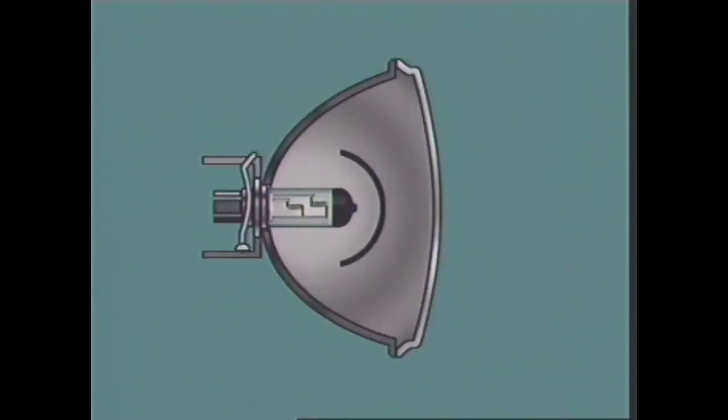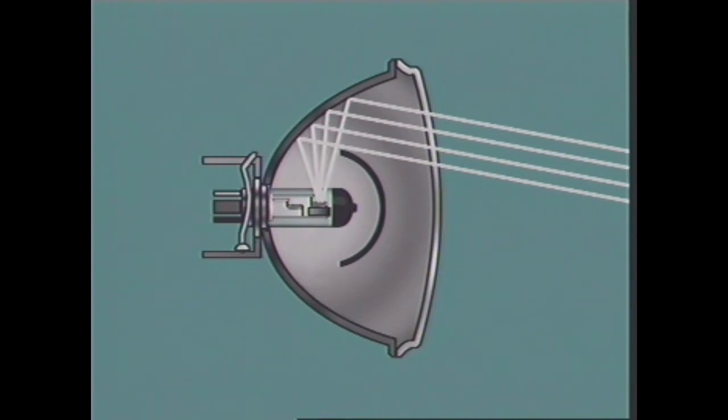Some headlight bulbs have a partial shield below the dip filament. This shield stops light from the filament striking the lower part of the reflector. The shield provides the primary shape of the dip beam. The final shaping of the beam is carried out by small cylindrical-shaped prisms in the headlight lens. This provides a dipped beam that is asymmetrical.